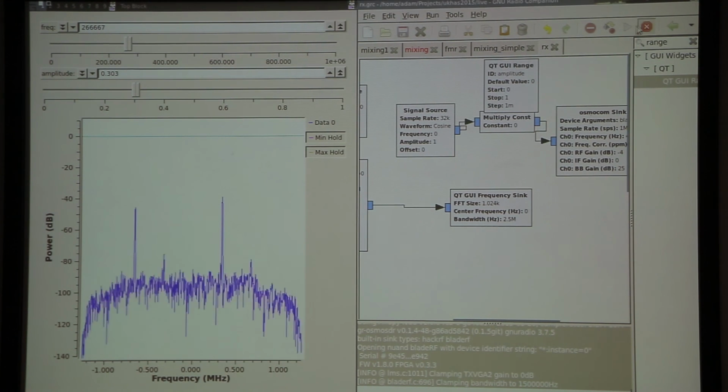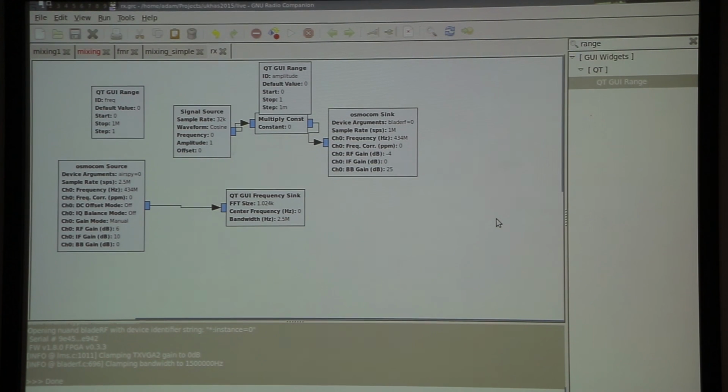Is that aliasing or harmonics, or just some antenna tuning thing I don't know about? So it will be, the transmitted signal is too strong, and on the receiver it's kind of distorting the incoming sine wave, which makes it look a bit more like a square wave. And the square wave has many harmonics of the same frequency, so that's what we're seeing here. The reason you see smaller ones going the other way is because it kind of keeps going into negative frequency, and those ones look like they're going the other way as we increase one frequency.